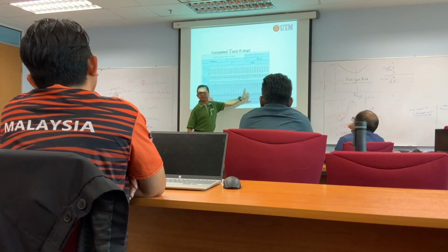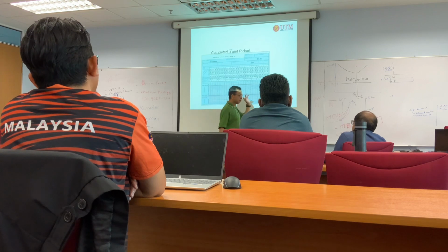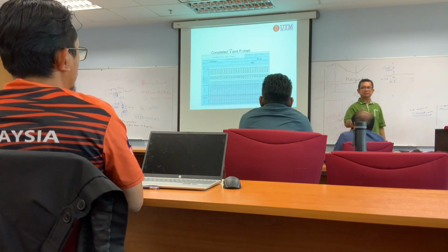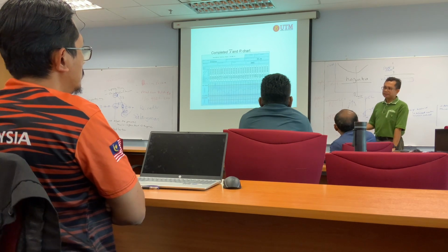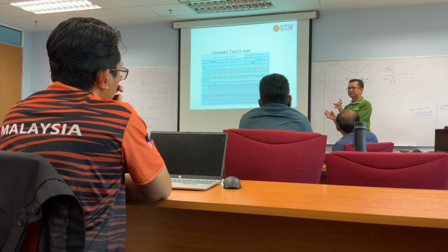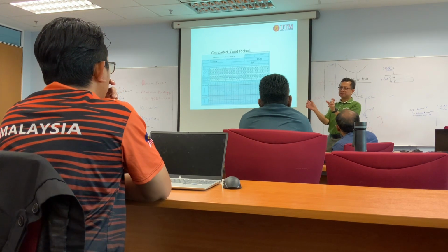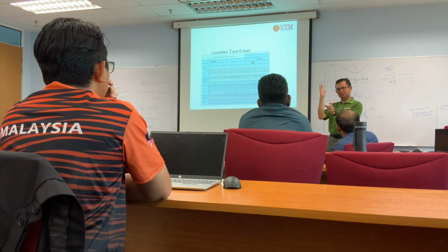When you want to use the standard deviation chart or the X bar chart depends on how many samples we have for each subgroup. Later I will show you. For this one, since we have only 4, it's reasonable to use average. But as engineers, we don't bother about whether it is standard deviation or average. The difference is very small. So why must we give ourselves a headache?